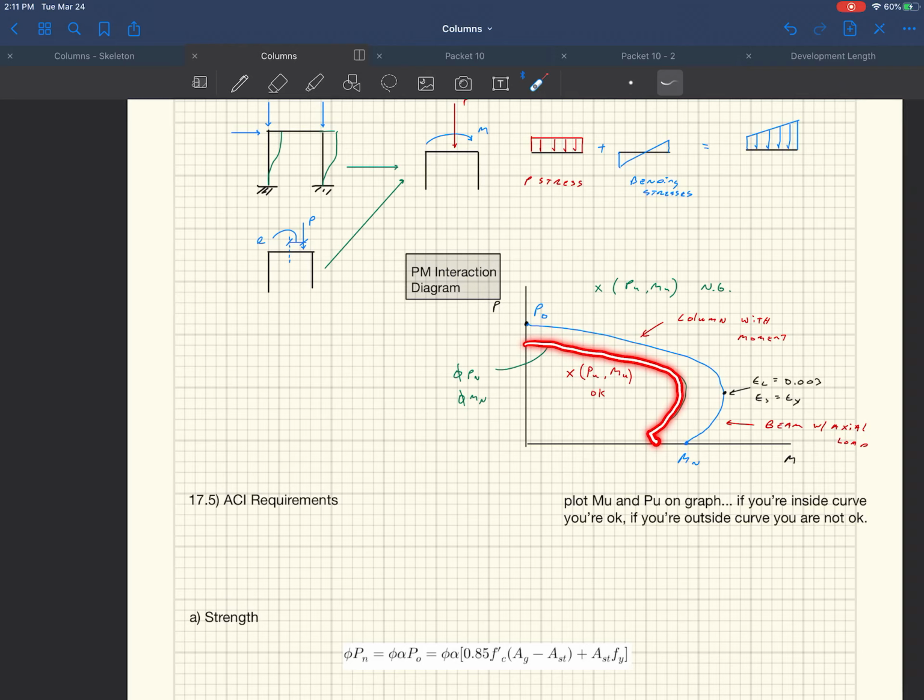They change with how much ductility you have in your beam, right? It's the same phi factors that we use for beam design, right? With the phi, how it changes between 0.65 and 0.9, right? When they change like that, that happens with columns as well.